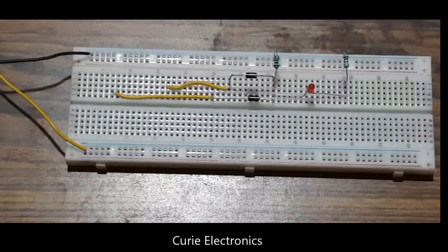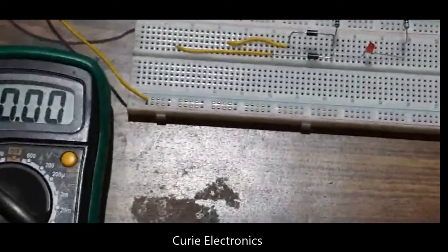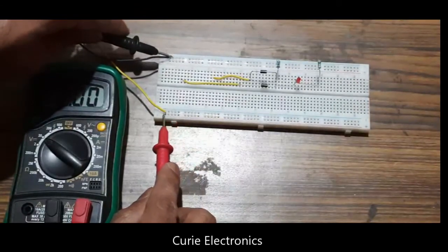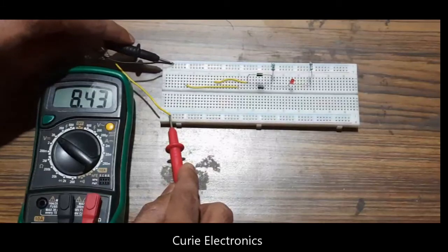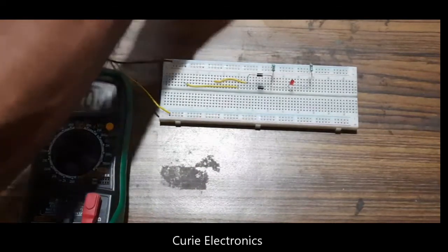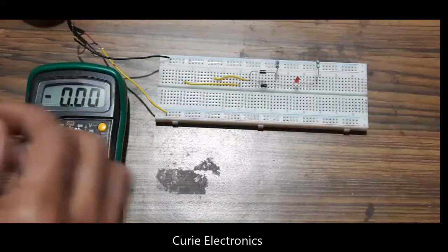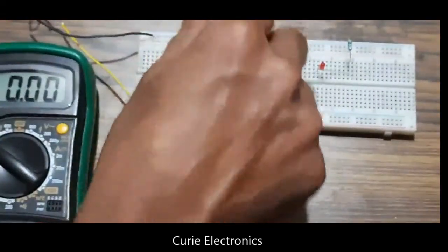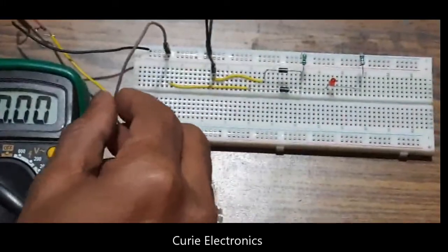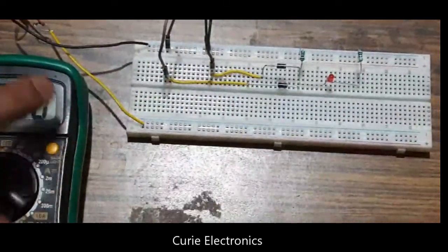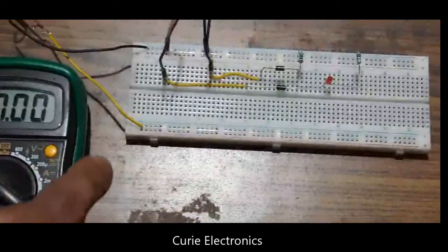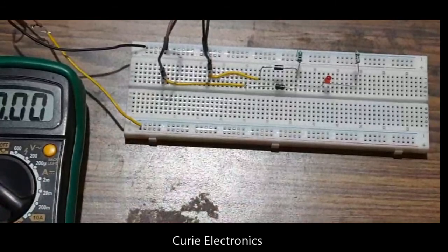Before giving the input, let's see the supplied voltage to this circuit. The supplied voltage is 5.16, same as the previous video. Now I will connect the inputs and see what is happening. First we will give the 0-0 combination. Both wires, I'll connect to the ground. The first input is connected to low, the second input is connected to low. You can see the black wire, this complete length, that blue line, indicates the negative line. Now the LED is off, that means our output is low.